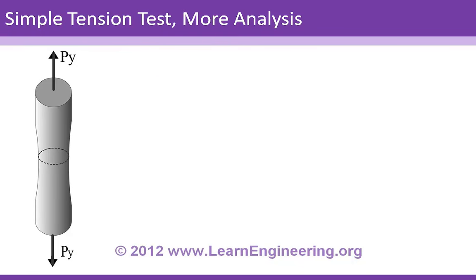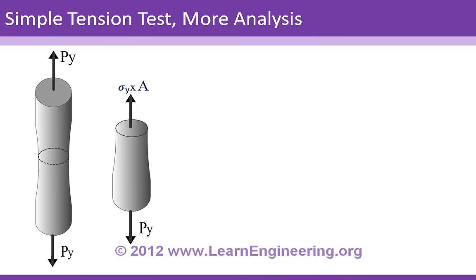Here it is. So assume your material has reached the yield limit, it is under yielding, so the force you applied is equivalent to that. Now what is the maximum normal stress induced at the time of yielding? It's very simple. This will be the same as the yield stress, because yield stress also is normal in direction. So maximum normal stress is the same as yield stress. And what's the maximum normal strain at the time of yielding? Maximum normal stress divided by Young's modulus gives you the maximum normal strain.